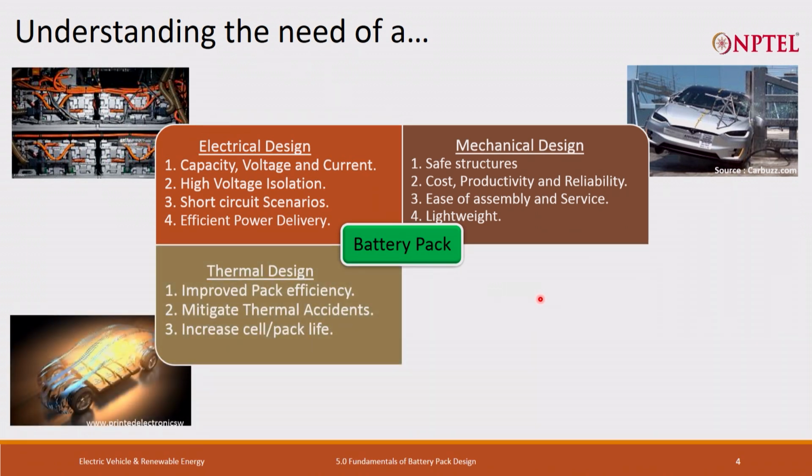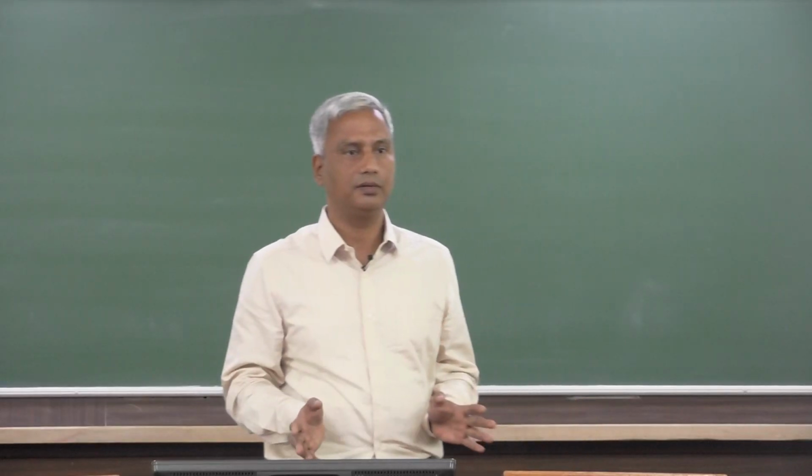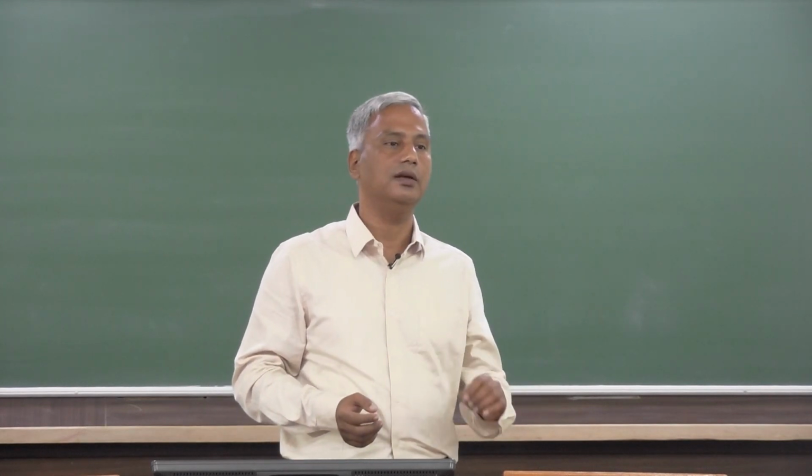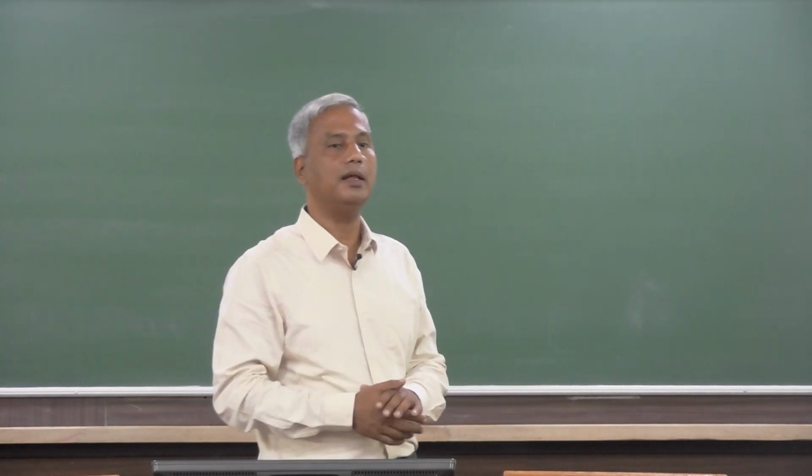Thermal design: from where are we taking the energy to run the thermal management system? We are taking the energy from the battery pack only. So, if the energy efficiency of the battery pack is good, I will take minimum energy to take out the heat generated by the battery pack.